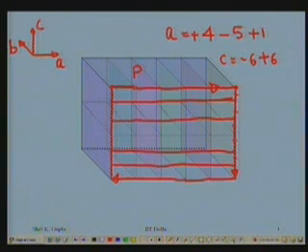So I start at P and end at P. It's the same point. Starting point and end point are the same. This is 0, this is 0. Now my Burgers circuit is complete. So when I have drawn this in a perfect region, the Burgers circuit has closed on itself because the net displacement of the path is 0. I'll just show this now in my edge dislocation, what happens.